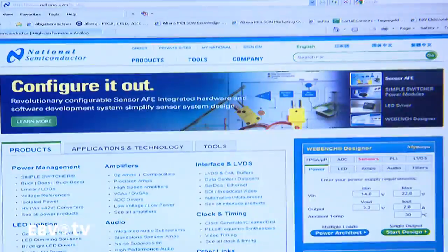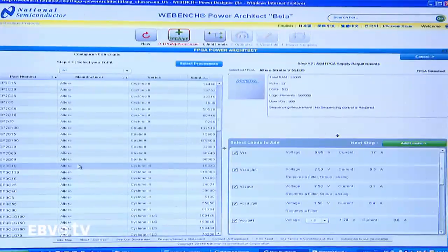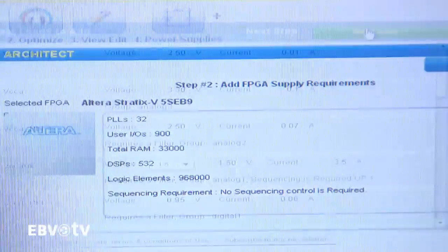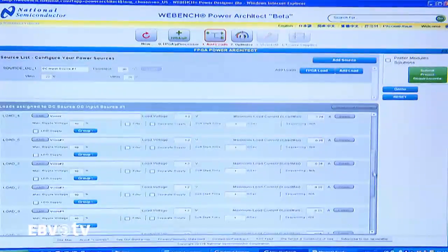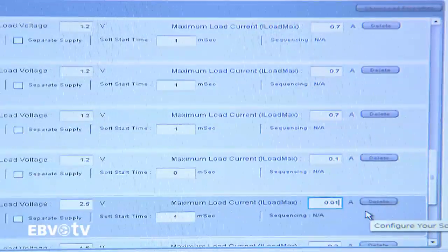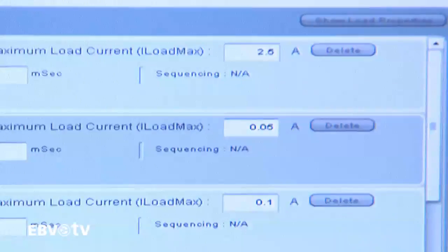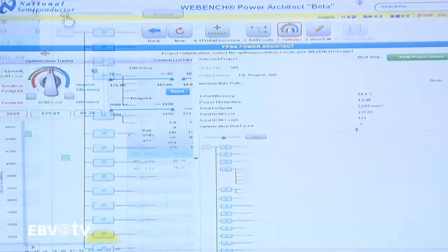Further to this, however, we have to take into account the requirements for the peripherals. Memory, flash, and I/O peripherals and their power requirements have to be added to the requirements of the core device. With this information, we can use Webbench to look for an optimal power design. First, we have to define the input voltage, temperature range, and the output voltages, which Webbench uses to produce proposals.